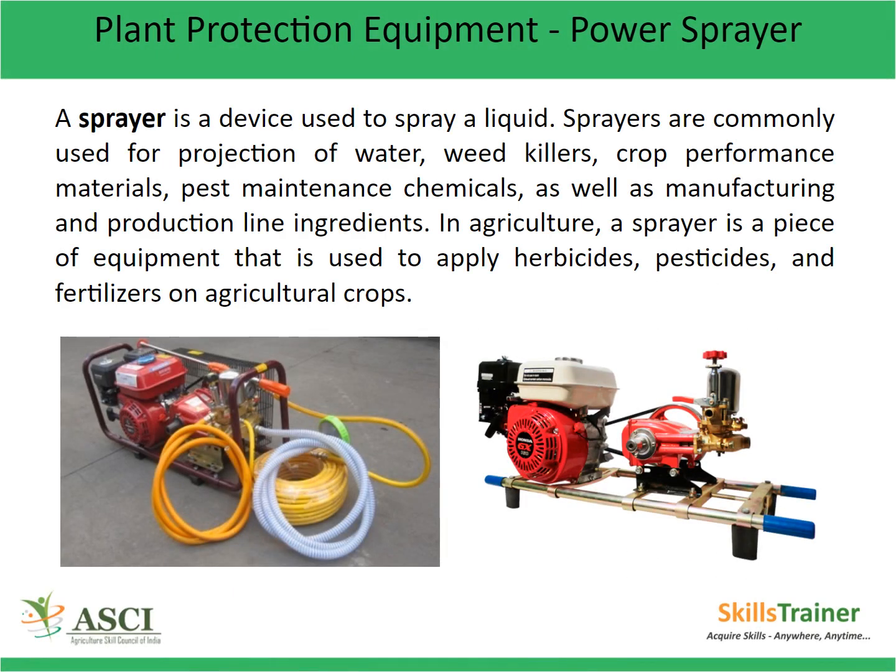Troubleshooting air filter. Never let the engine run without the air filter. A dirty air filter element affects the engine performance, increases fuel consumption, and makes it difficult to start. If you notice a loss of engine power,